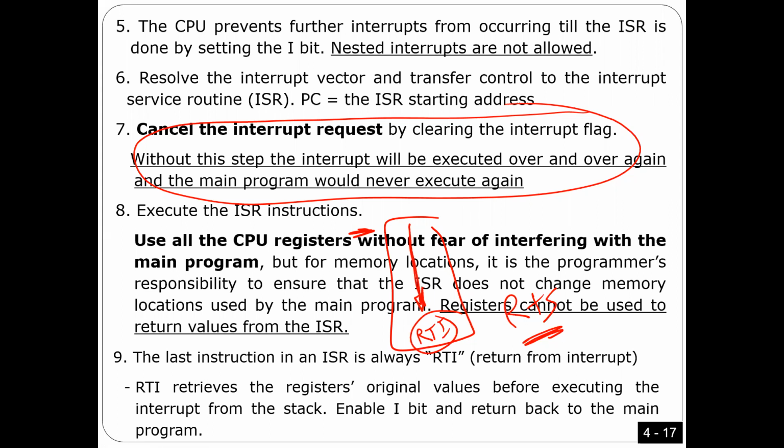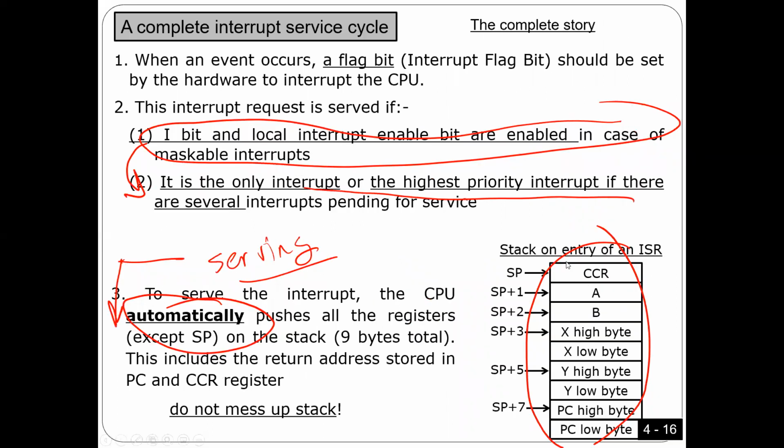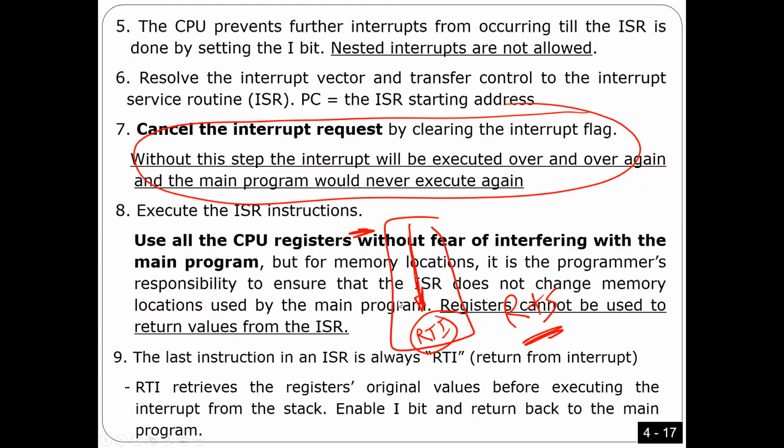okay? On top of that, it's going to do one more thing, okay? What it's going to do is pull all registers back, okay? So that means RTI is similar to RTS, but it has to do one thing more. It has to pull all the registers from the stack, okay, guys? So this is the whole story.